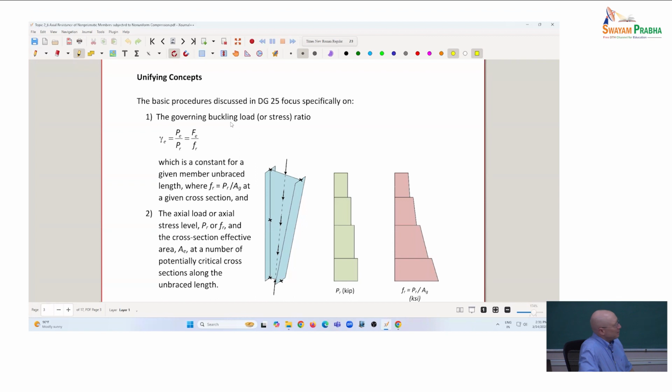So here's some hypothetical tapered column with several axial loads coming on the column along the length. There's X's, maybe they represent brace points where we're preventing out-of-plane movement of the section. Looks like we've got there in the middle just maybe a brace point that's an attachment of a girt, maybe on the outside flange, but there's not a flange diagonal to the inside flange. Okay, so how do we approach this?